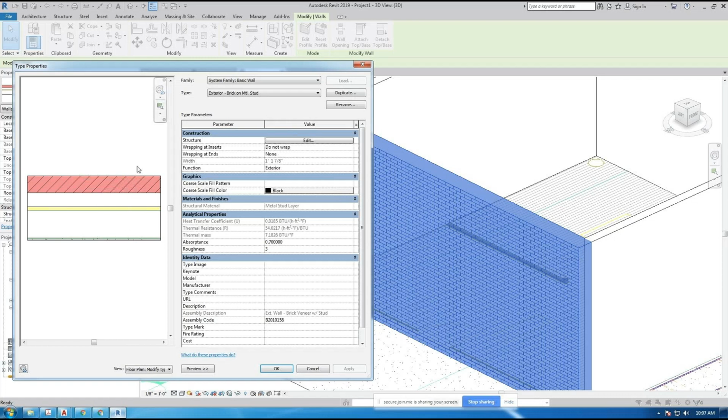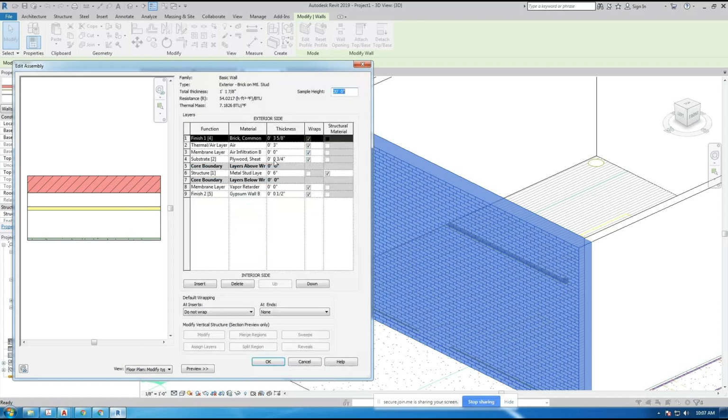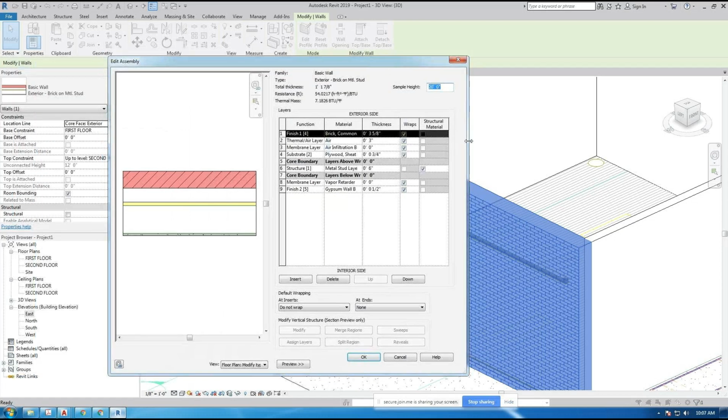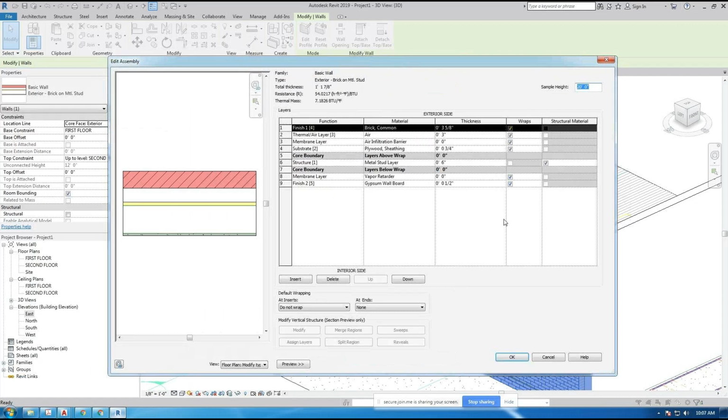There's different color codes here. This is a cross section through the wall. Imagine slicing through the wall, looking down. All the materials that make up the wall are here. When I go to structure, it tells me what those materials are. And here it becomes a little more clearer. So, function is a way of flagging what these walls are used for. If you look at the list, they basically organize the data and let you determine, oh, this is used for the exterior, the interior, the finish, what have you. Not hugely important at this moment, but there are different settings here that you can change.